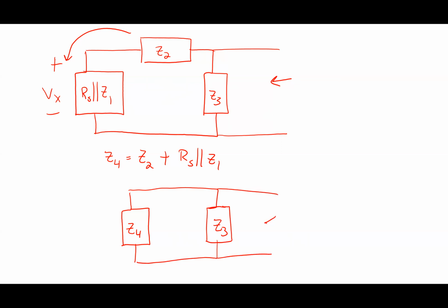All right, now I still want to find the impedance looking into this guy. Well, what is that? The voltages across those two impedances are the same, right? So the voltages across them are the same. Then what do I know about them? They're in parallel, right? So now at that point, I can reduce this whole network to one impedance, which I'll write as ZEQ.